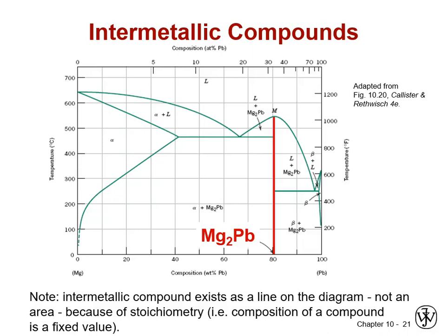Okay, special constituents. These are components. Intermetallic compounds. There are certain metals that like to sit in association with one another. These are almost akin to a ceramic bond. They're still metallic bonds, but a lot of them have quite a bit of covalent flavor to them. They tend to be very, very stable.